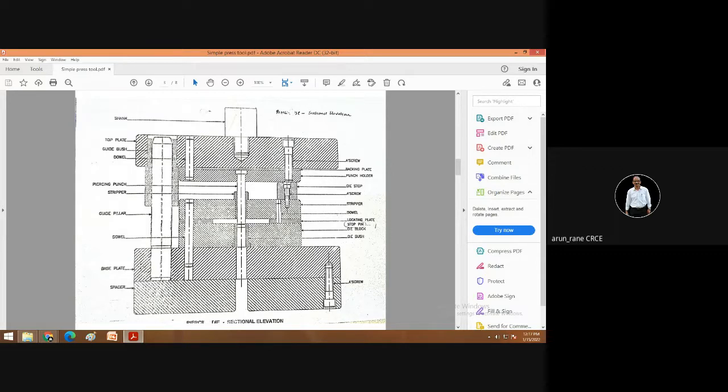इसके ऊपर this is base plate, then this is your डाई ब्लॉक. डाई ब्लॉक में हम लोग बुश डालते हैं, जिसको कि डाई बुश बोलते हैं, और डाई बुश में आपका साइज आएगा, डाई साइज. सो दिस इज योर पंच साइज and this is your die size. So if it is blanking, then clearance is given on the punch. Punch is small. If it is piercing, then clearance is given on blanking on the die. So die size is bigger.